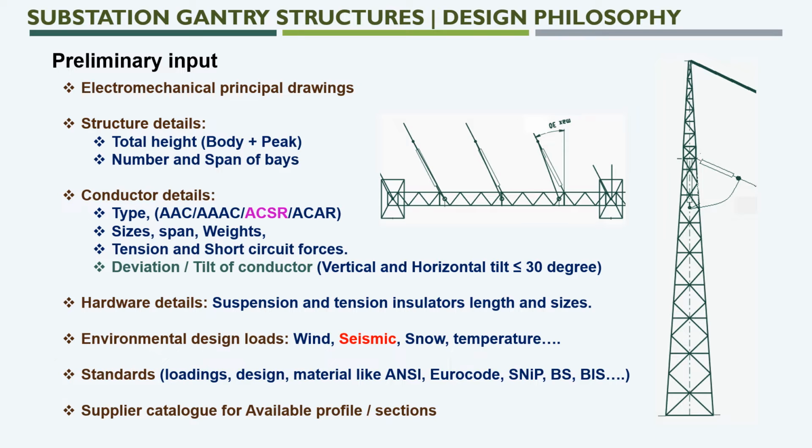In order to arrest the sag, there will be a tension to be applied at both ends of the conductor. So this will impact the structure girder. So the tension value also we need to calculate. Generally, in a country where snow and minimum temperature are not envisaged, for that condition we can consider only the dead weight of the conductor and apply the formula WL square by